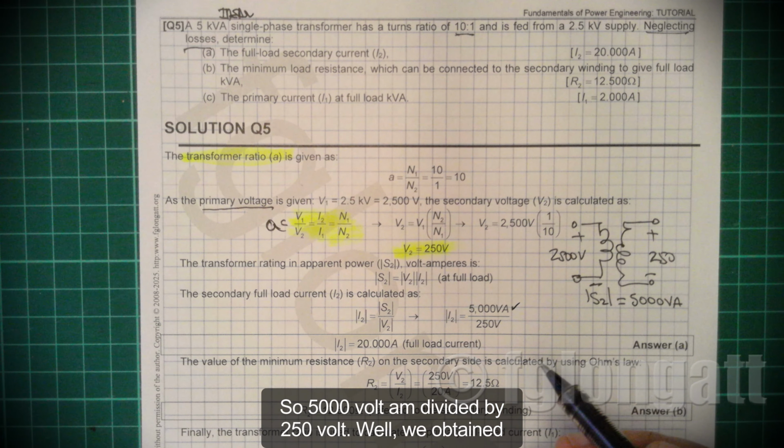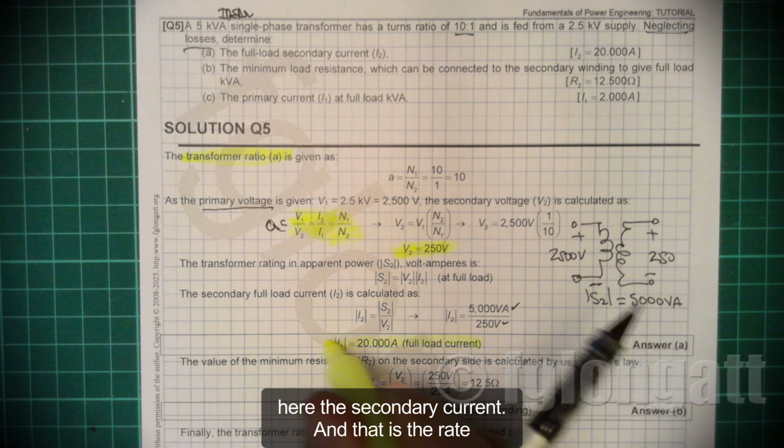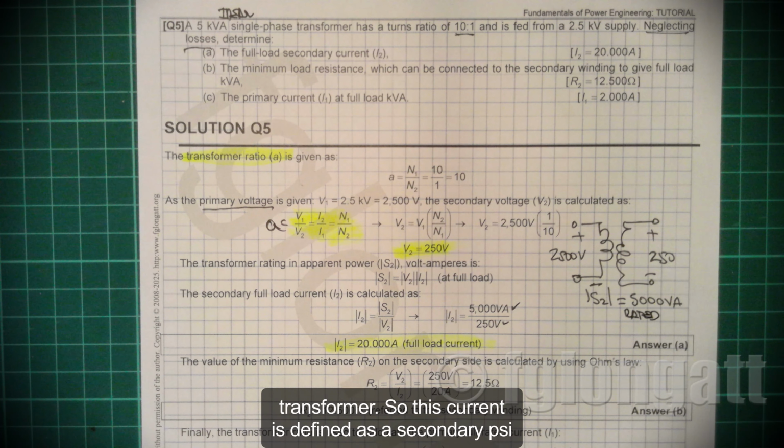So 5000 volt amps divided by 250 volts. We obtain the rated secondary current, because this is the rated power of the transformer. This current is defined at the secondary side: 20 amps.